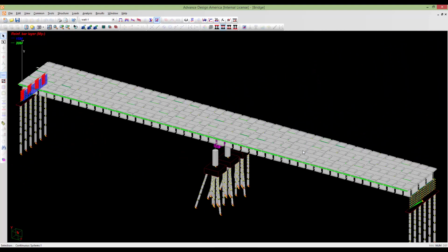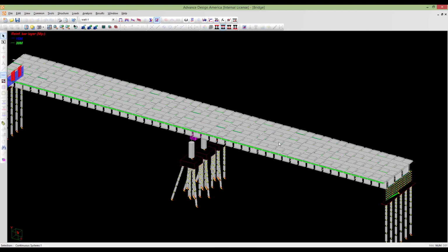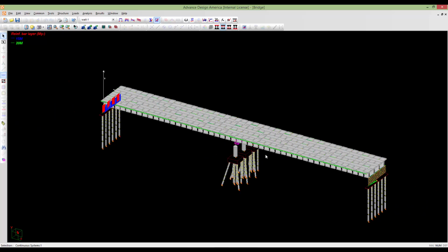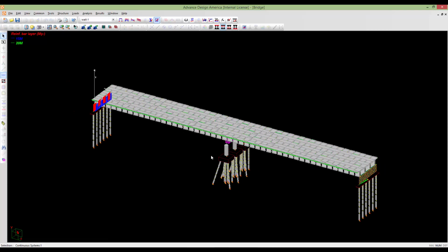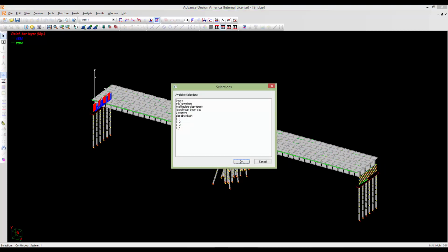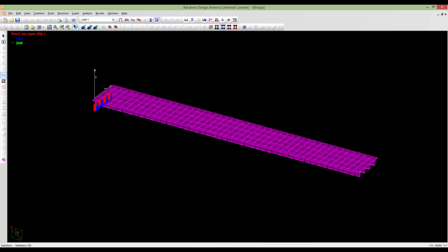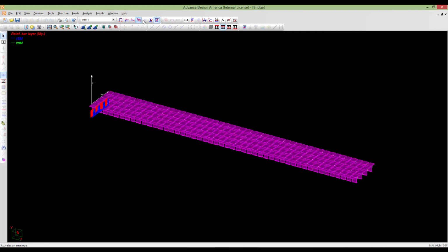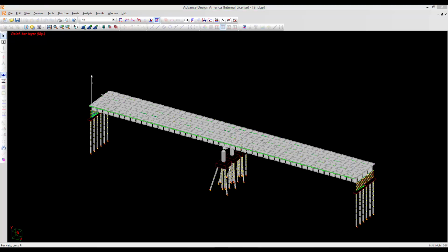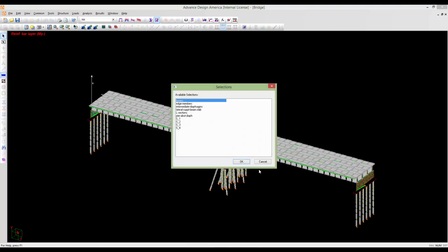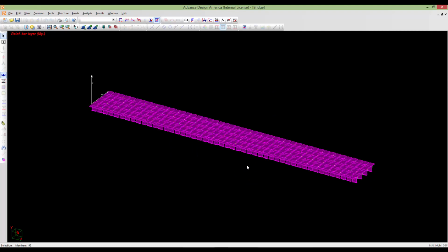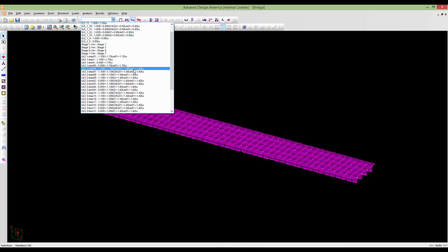And also, if you want to check internal force diagrams, you can use Control K to mask your beams, and put it as nil here. Control K, beams, mask. And from here, you have access to all of the stages.